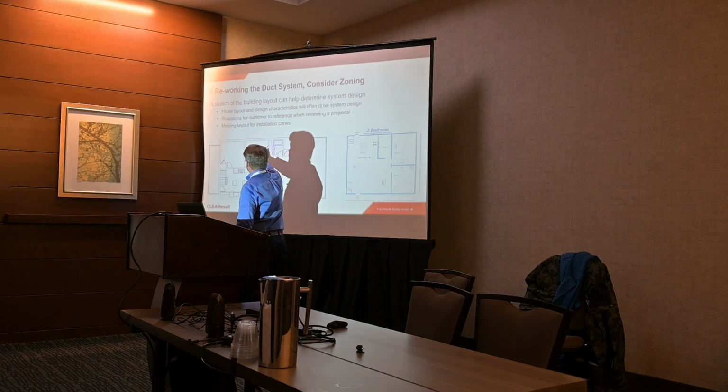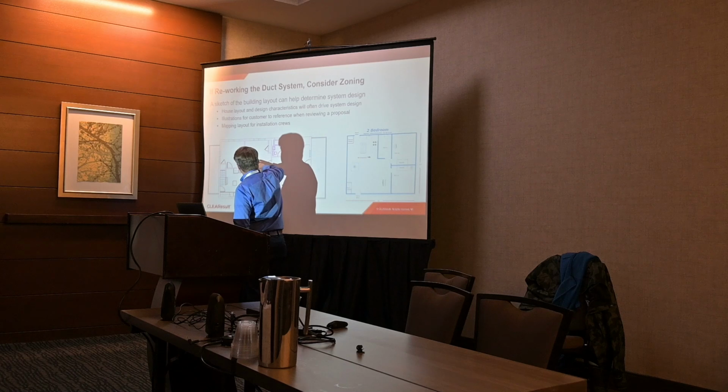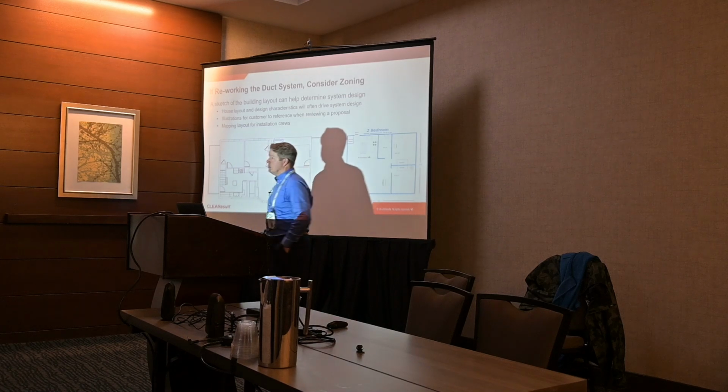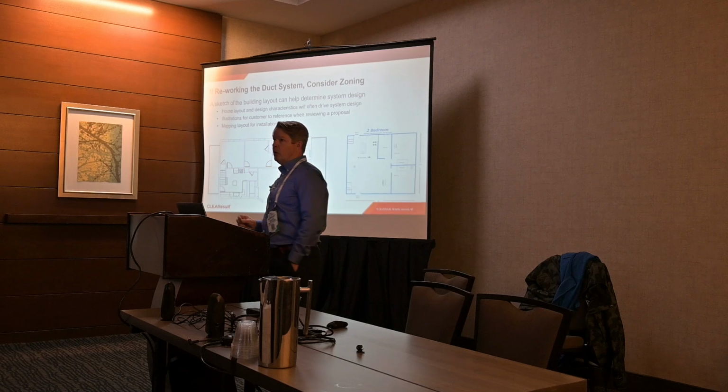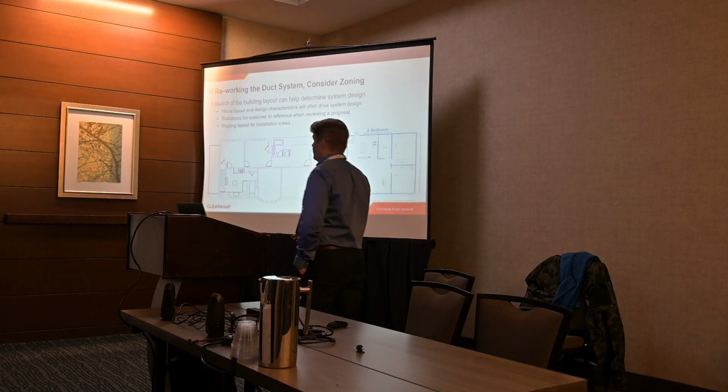It's only 700 or 800 BTUs per hour. We don't want a 3,000 BTU head in there. It's too big, right? It's still too big regardless. So what we can do is come to a small air handler with very short duct runs, and one stage of capacity can serve all 3 or all 4 of those rooms, right? And that more closely matches it to the load on the room, which is our goal, right? Not to oversize or undersize, but to exactly size it if we can.